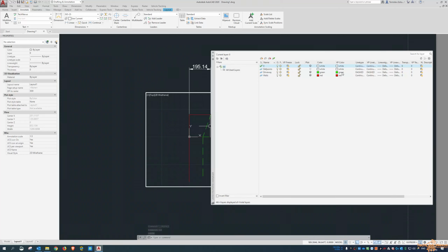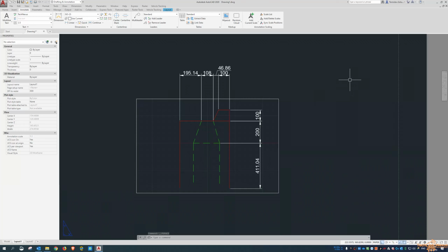Okay, and with the layering command, you can freeze certain layers in certain viewports. You can adjust the colors for that viewport, so you can see the main color will be green, but for this viewport we can make it a different color if you really need to. So have a look at exploring those options. I won't necessarily delve into it just now, just to keep this video short and sweet, but if you do have any questions about layers and how they work, feel free to make comments in the comment section below, and I can have a bit of a dive into the layers, and then you can see how much more powerful the layers can be.